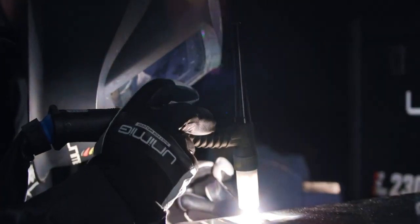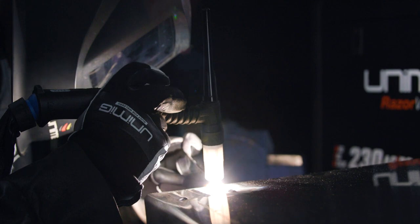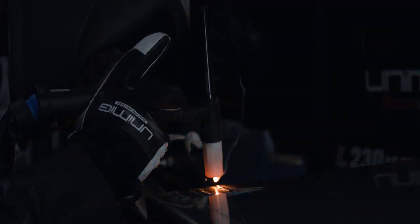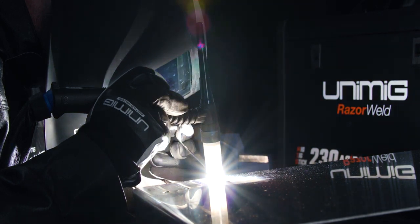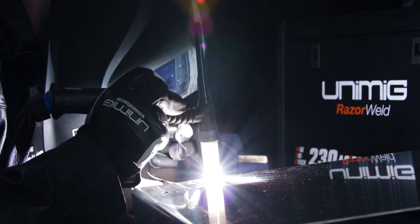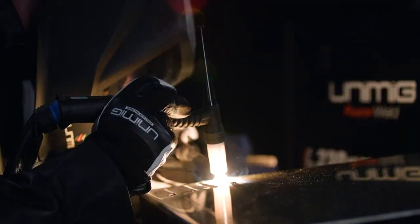While welding, push the torch trigger to switch to the HC base amps. To end the weld, hold the torch trigger. HCT mode is great for manual heat input control in the weld. It works like a manual pulse mode. Spot mode will produce a series of consecutive and evenly timed arcs, perfect for even tacks and small welds. When in spot mode, you can select how long you want the arc to be on. When the trigger is pressed, the torch will only weld for the set amount of time.